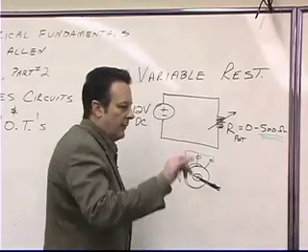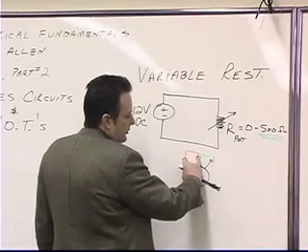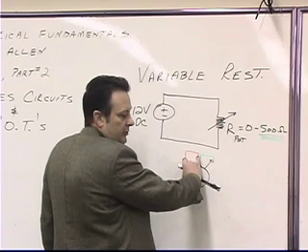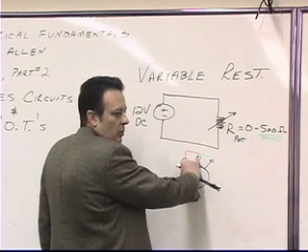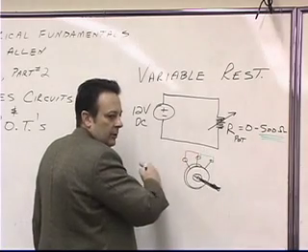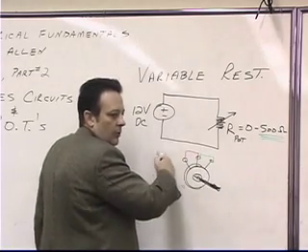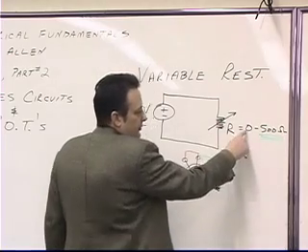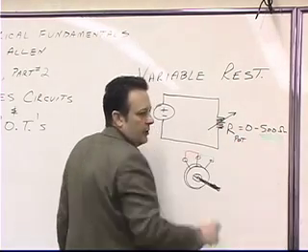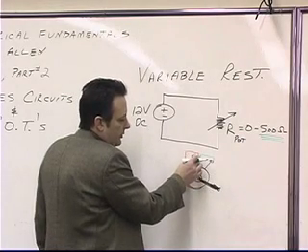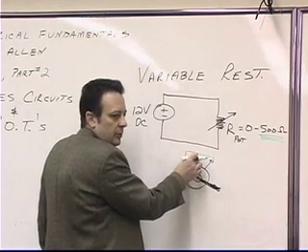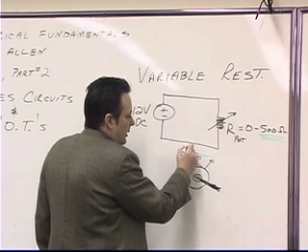Okay? On the other hand, if you connect the center post of the potentiometer and the outermost left post of the potentiometer, you're going to be getting one extreme, either the low side or the high side. So let's say that this can go from 0 to 500 ohms. And let's say that you had turned the knob so that the resistance between these two posts right here measured 50 ohms.